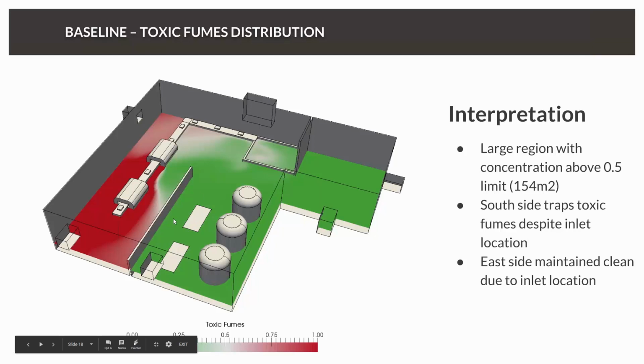As you can see, basically right now, it is fine for the working area, but also around the coating station are people who are working, and here the concentration is much too high. 0.5 would be okay for this region, 0.25 or below is necessary for this region, but 0.75 is undiscussable.